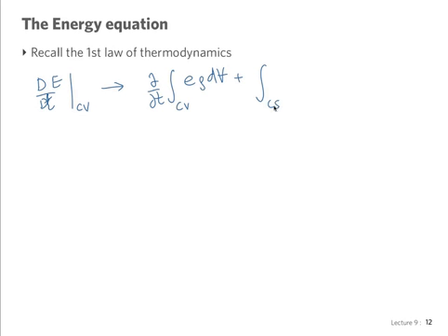So control surface, and we have the flux of energy due to the fact that there's movement of fluid, right? So fluid is coming in or out of our control volume. Control volume is fixed, remember, a black box, and as the fluid goes in with a certain velocity, for example, we could have one inlet, one outlet, the simplest case, then it carries with it energy.